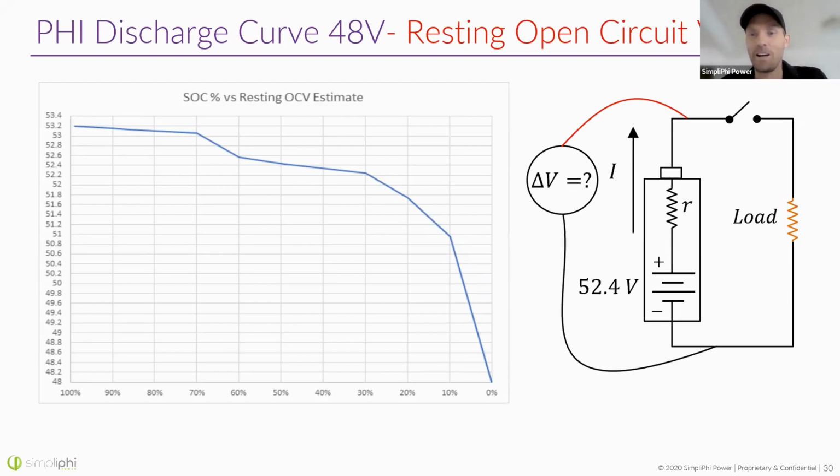James writes, how well tested are the heating pads for the batteries that you sell? If the battery is an Amplify battery that turns off due to cold, then we'll power the heating pad. Yeah, so we sell heating pads that sit underneath the batteries that run off of the battery itself, and they're wired into the BMS. They are special order, but they're good for operating in low temperature environments.